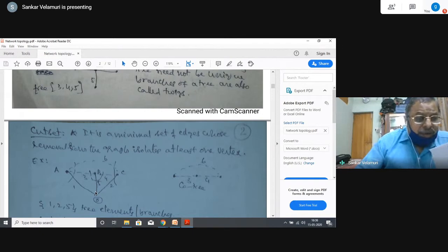Do not confuse how the voltage sources, dependent sources, and other things are there. Only the element graph is being drawn. Whether it is a dependent source, resistance, inductance or capacitance, nobody has stated, but it is represented as a graph. So how many loop equations are required? 3 loop equations, because there are only 3 links, although there are 6 elements shown in the graph.